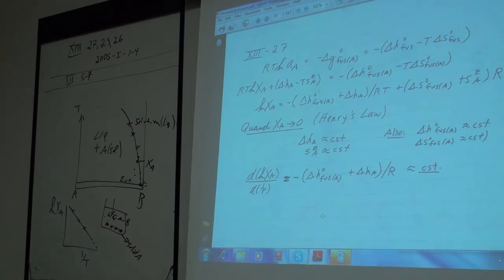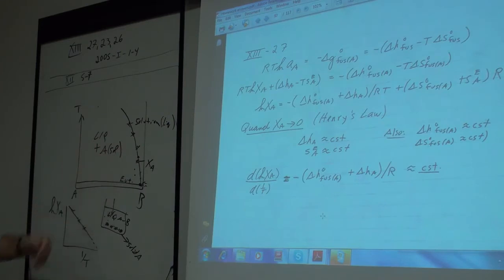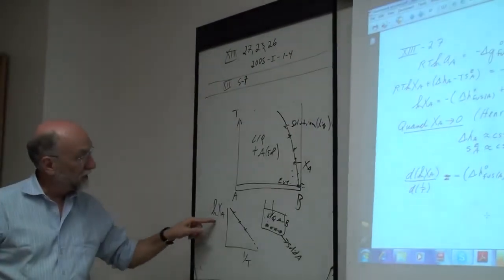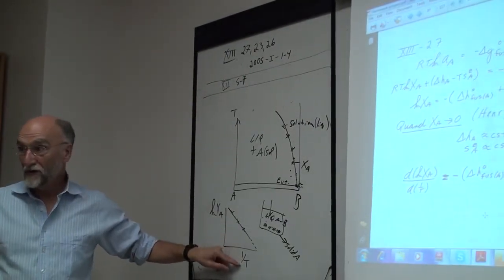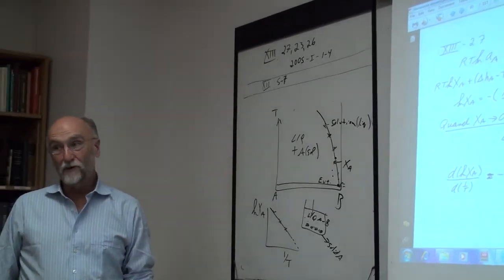Another thing, if you're doing your phase diagram optimizations, and you take a solubility curve, I mean a liquidus, with just a few percent solubility and measurements along it, just replot it this way. Take the experimental points and plot them as log XA versus 1 over T. If it's not a straight line, or close to a straight line, then you know probably something's wrong with those measurements.